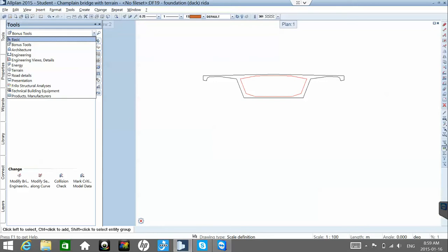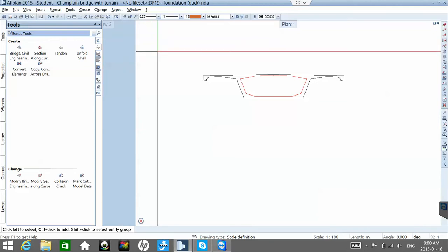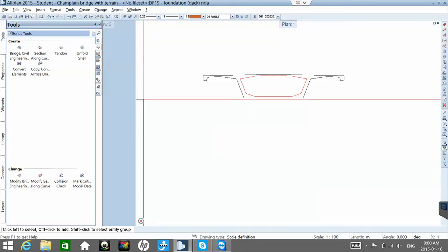Upwards, it's a button called, so just leave the mouse a bit for me to take control. So here on the top side near these eyes, this one, hidden line image wireframe. This can help us convert what we see on the screen into 2D representation. And this is how we also can avoid a double line. So you do the operations now.